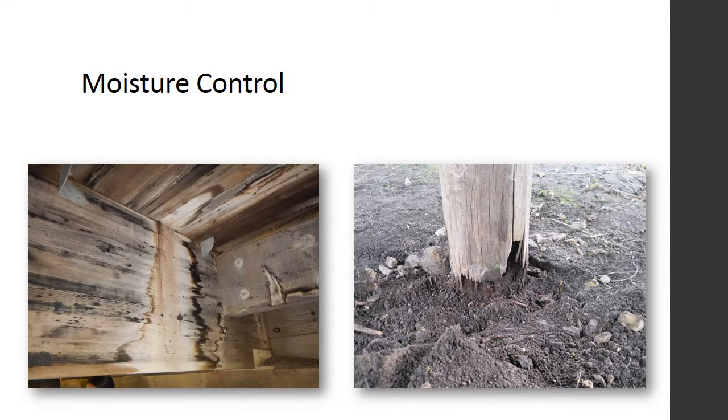The simplest preventative maintenance for timber is moisture control. Most commonly, the members subjected to elevated moisture levels are those at or near the ground and/or water line, if at a water crossing such as timber piles. Even so, other bridge elements should be observed for potential moisture problems. Moisture control can be used as an effective technique to extend the service life of many timber elements.